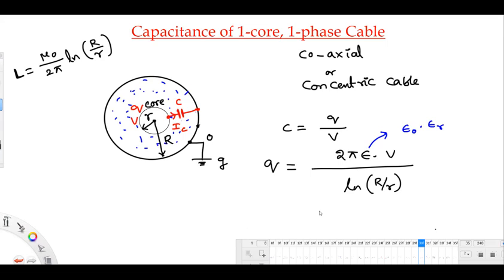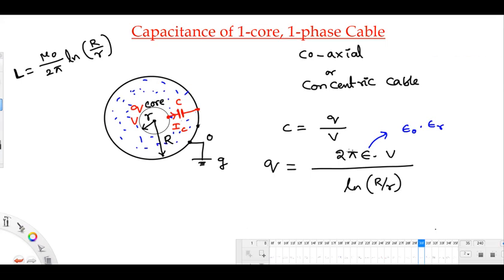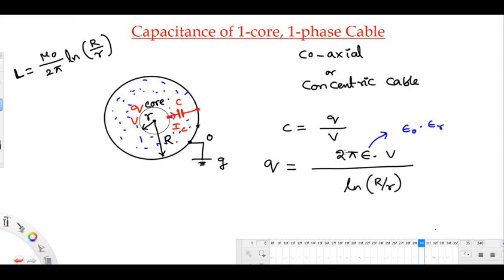Sir, yesterday I discussed one problem regarding the phase modifier, with the three power equivalent 1000 kilowatt. In that question, if we use this method, we have P1, P2, P3 and cos phi 1, cos phi 2, cos phi 3, and we calculate S, and when we take S1 plus S2 plus S3 and calculate cos phi, why is that method wrong?